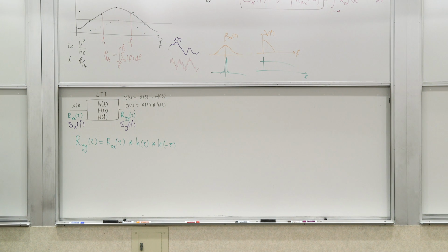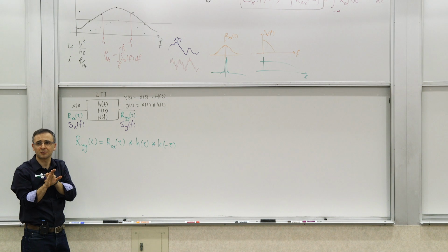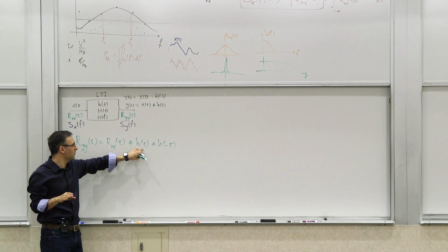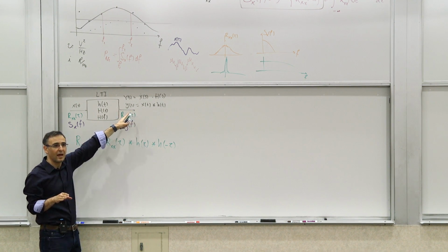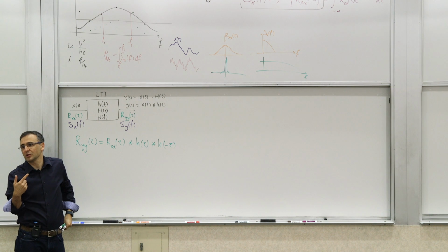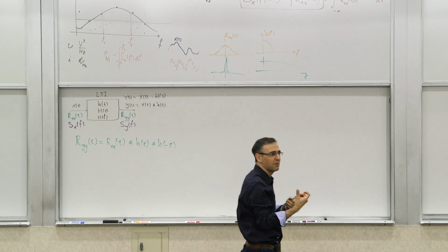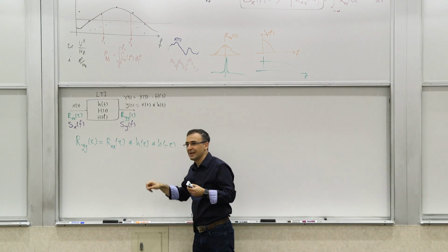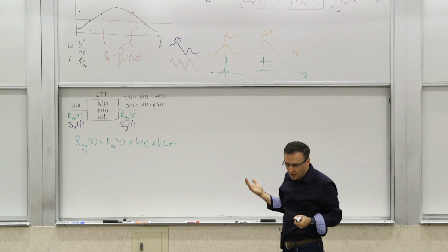Now for random signals, this is what you get. The way you do it, you will get three nested integrals, one for the autocorrelation function and one for each of the convolutions that you get for y of t. Then you need to reorder the integration. You just switch the order of integrations, and then you can simplify it, and you will easily see that this comes out. It's a little bit messy in terms of calculation, but it's not very profound.